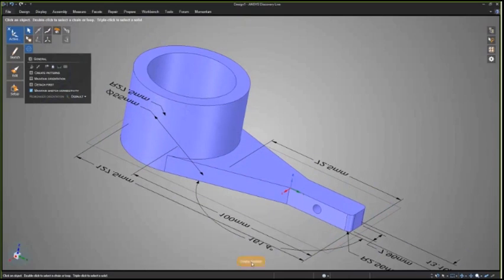So we're here in Live, and anytime you want to add simulation to your design, you want to create a solution. Discovery Live currently can do 4 independent types of physics. It can do a thermal study, it can do fluid behavior, both internal and external, it can do static structural, and we can also look at modal. Now, there are certain limitations, we'll call them for now. For example, structural only does linear materials and bonded contacts. Different types of materials and contacts, conjugate heat transfer, combining thermal and fluids, is on our future roadmap. It is something we're working on, so keep your eyes open for future releases to see more of this.